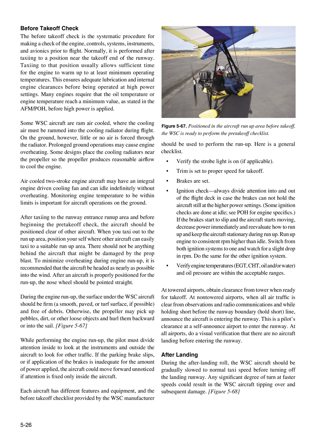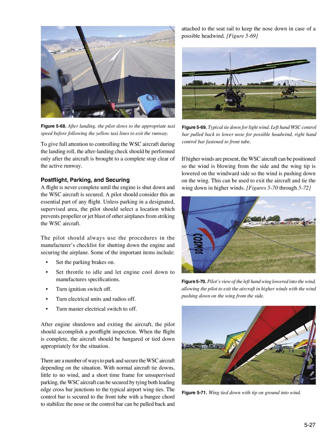After landing, during the after-landing roll, the WSC aircraft should be gradually slowed to normal taxi speed before turning off the landing runway. Any significant degree of turn at faster speeds could result in the WSC aircraft tipping over and subsequent damage. Figure 5-68. To give full attention to controlling the WSC aircraft during the landing roll, the after-landing check should be performed only after the aircraft is brought to a complete stop clear of the active runway.